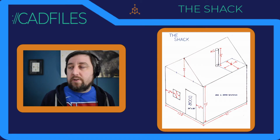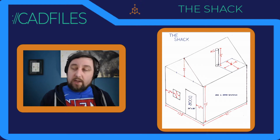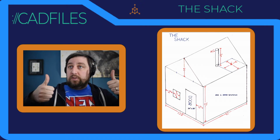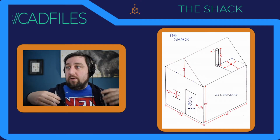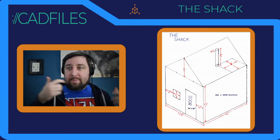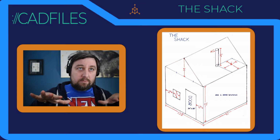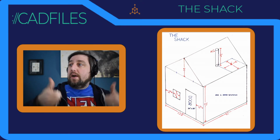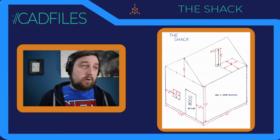So for our entire shack, we're going to draw just a 2D flat surface on the bottom, and then we're going to pull it up. In SketchUp, it's called press pull. In Onshape 3D modeling, it's called extrude. All the same kind of idea. Take a 2D drawing, in this case a rectangle, and then pull it up to be 3D. So this one is 10.5 feet, or 10 feet 6 inches,